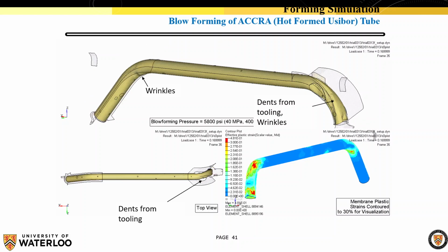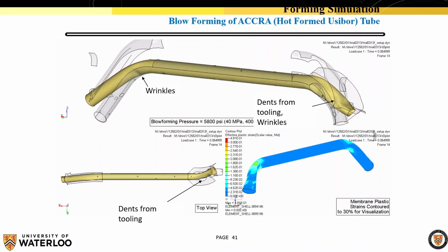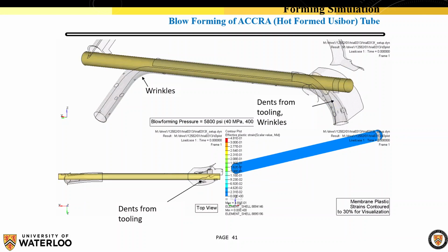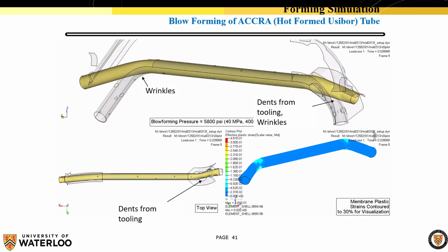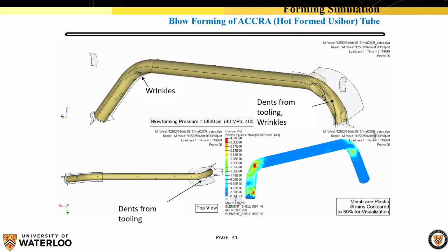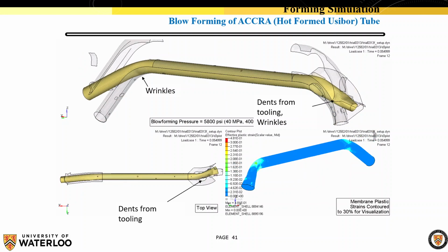A little bit of both. That's an excellent question. I don't know what your solid mechanics course would have looked like, but if you remember an I-beam, a structure that has some cross-sectional properties, if you put some defect in it, no matter what you do when you bend it, it's going to initiate a failure in that location. So part of it is aesthetic. A lot of this is covered now with plastic in cars, so you don't really see it, but a lot of it is aesthetic, and some of it has to do with structure as well. So very good question.